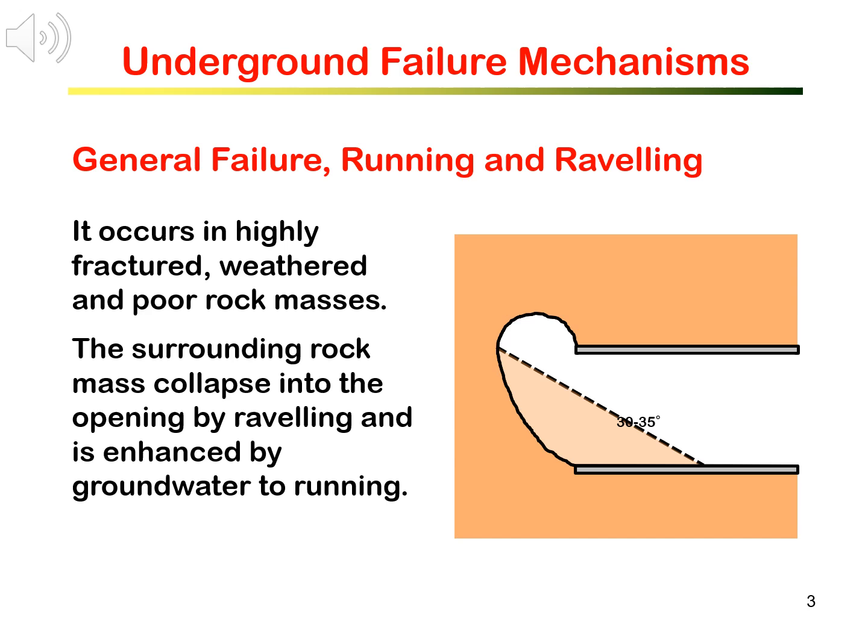Usually, tunneling in this type of ground is well supported to prevent such a failure. The support must be in place immediately after the excavation. For example, using the shield tunneling machine so that the circumference of the excavated tunnel is always supported. If in really unstable ground, the excavation face can also be supported during excavation.